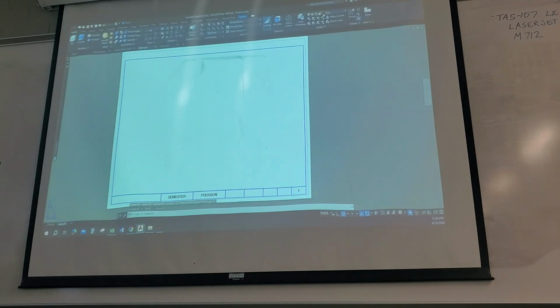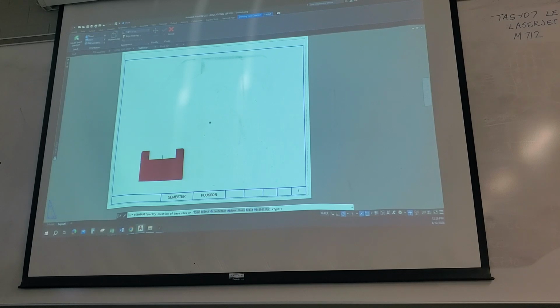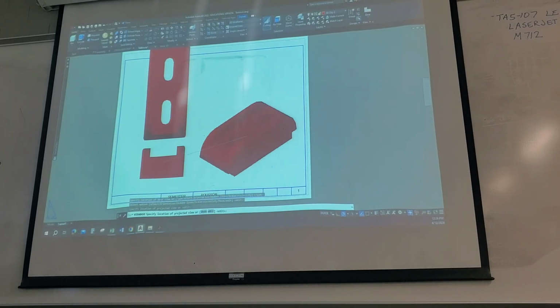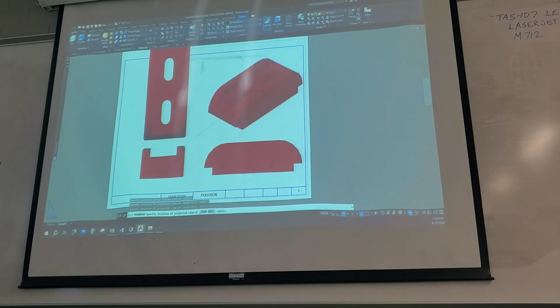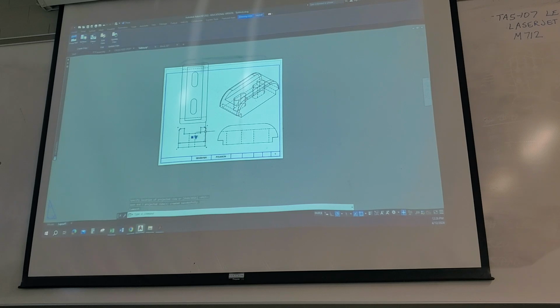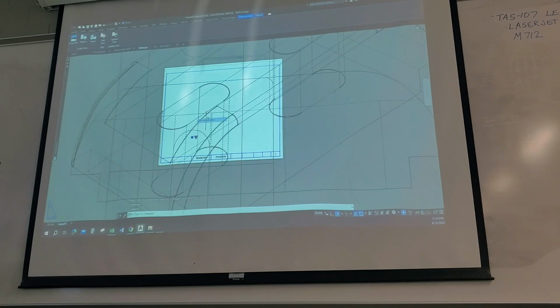I'm going to switch to one of my object layers, or my only object layer. Base command from model space, front view, hit enter, space bar, top view, right side view, isometric, space bar to complete it. So this one right here doesn't look like it's fitting, so I'm not gonna fight it, try to make it tight, scrunched up.